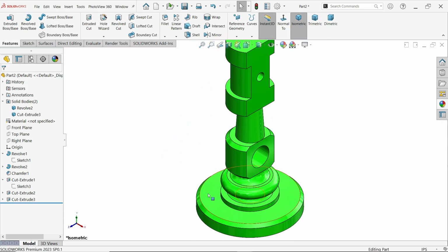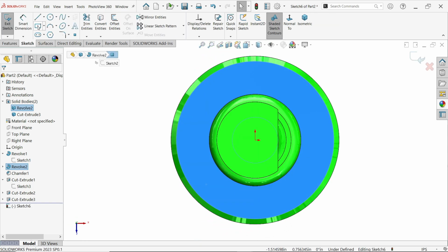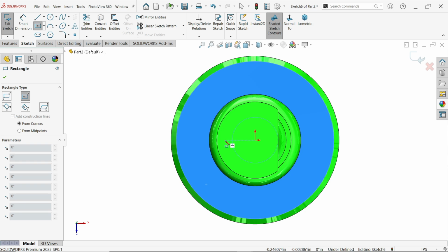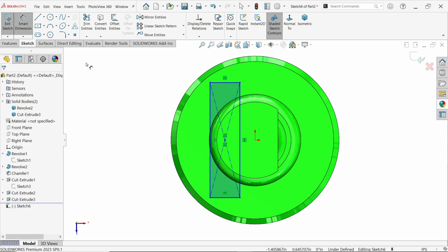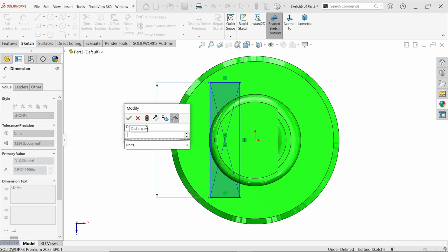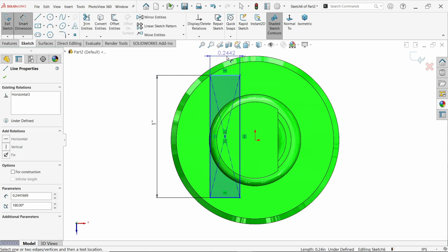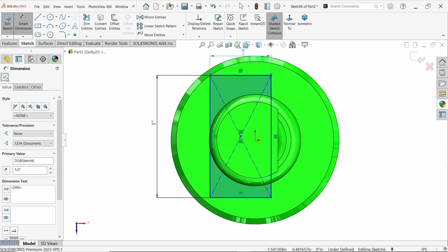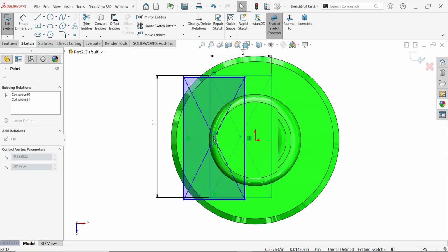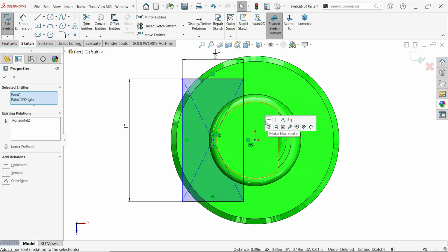Now again we need to cut back side, so select this face, sketch. Now again I am going to draw one rectangle, escape key to out. Now let's make little bigger, let's say 1 inch, and this is also defined something like 0.5 inch, okay. Just drag somewhere out, hold shift key, select these 2 points horizontal.